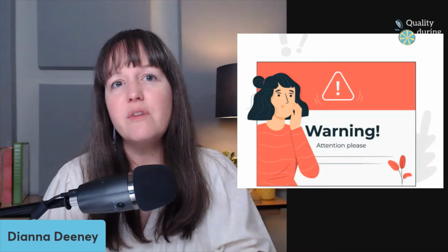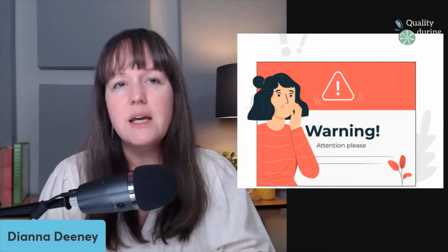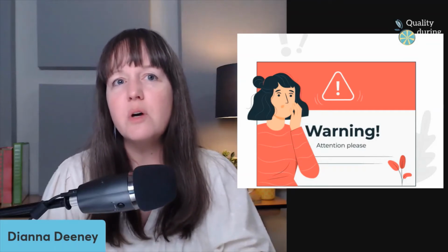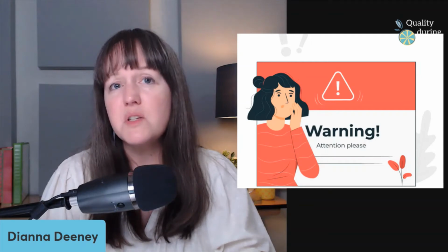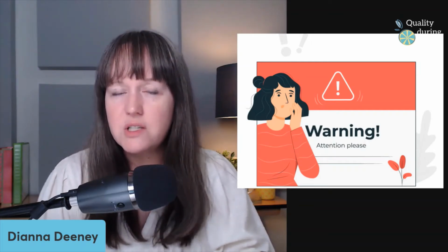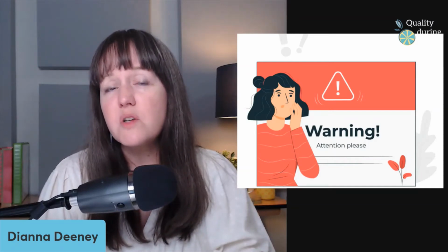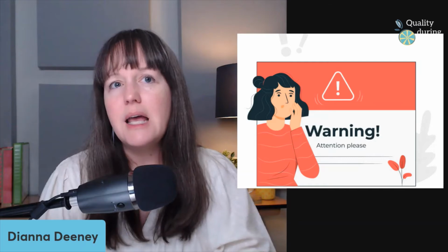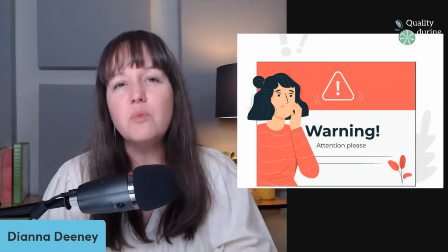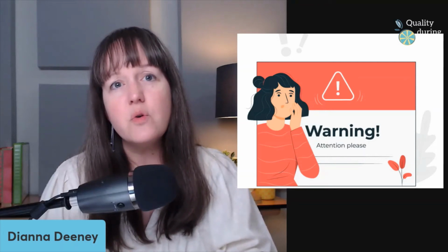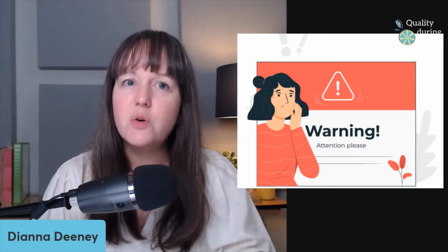Detection controls affect our ability to notice or pick out when there's been an error or issue. Detection controls require someone or something to monitor. It could be inspection performed by quality personnel, or by an automated vision system. It could be an internal system check that monitors and reports on inputs or outputs. It can be an anomaly detection using machine learning. We can rate the effectiveness of our detection controls on the likelihood that they'll help us or some other monitoring system notice an issue.